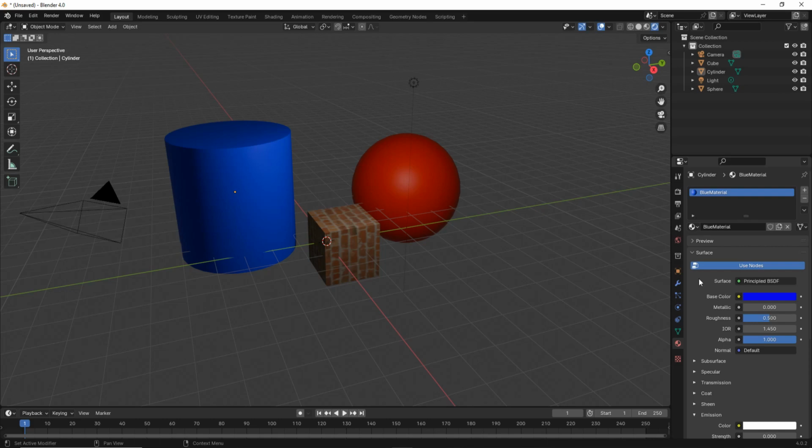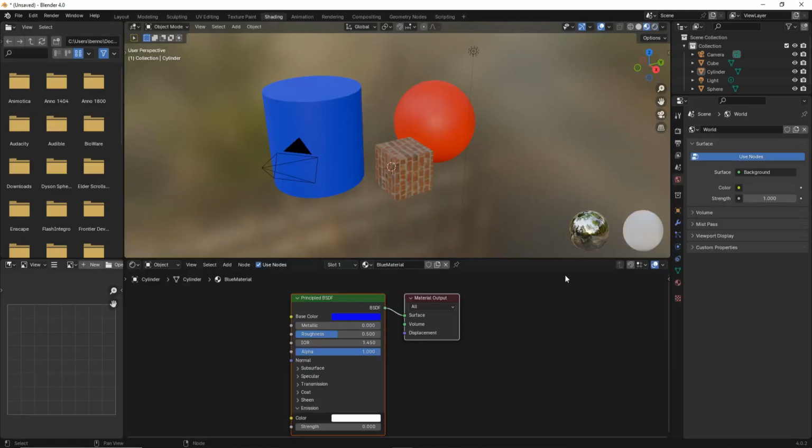For now, let's stick to the principled BSDF and the base color of your choosing, and then metallicness of 0. And let's go to the shading tab. In here, we can actually change all of the inputs of our surface model with different kinds of algorithm, different kinds of input, or even texture files.